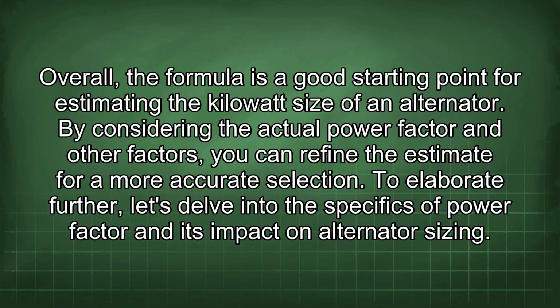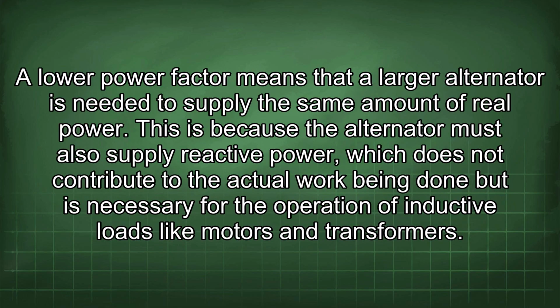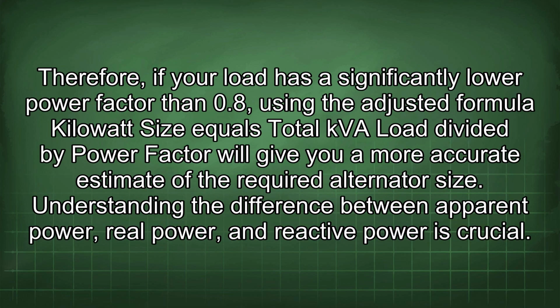To elaborate further, let's delve into the specifics of power factor and its impact on alternator sizing. A lower power factor means that a larger alternator is needed to supply the same amount of real power. This is because the alternator must also supply reactive power, which does not contribute to the actual work being done but is necessary for the operation of inductive loads like motors and transformers. Therefore, if your load has a significantly lower power factor than 0.8, using the adjusted formula kilowatt size equals total kVA load divided by power factor will give you a more accurate estimate of the required alternator size.